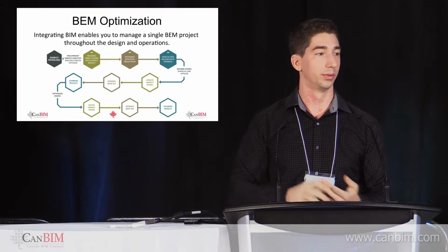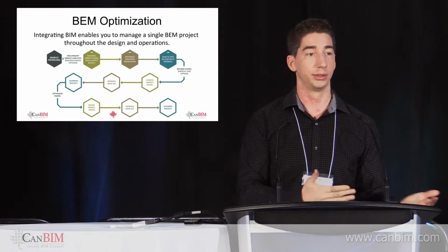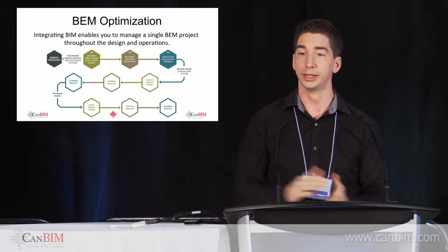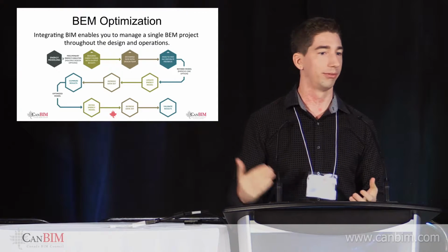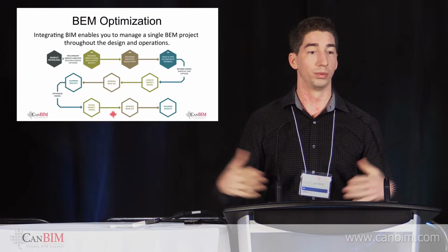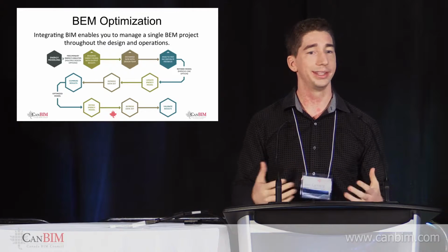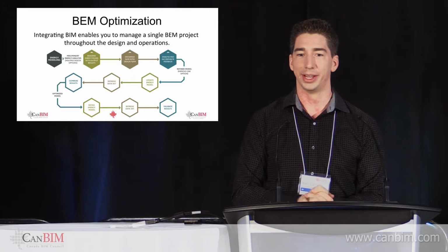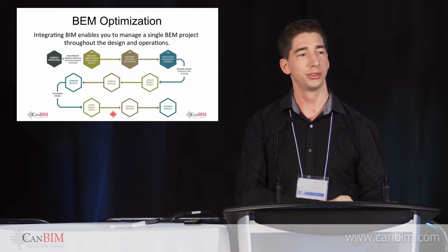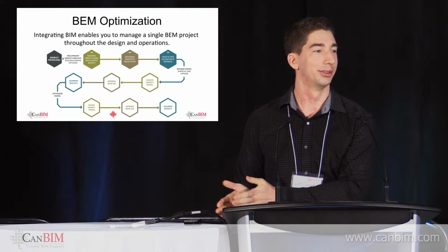A lot of the time, we're doing code compliance work. We're seeing where you're going to end up for your LEED credits, and we're doing that really, really early. If you're not satisfied with 5% above code just to get your building permit, you might actually want to reduce your window-wall ratio or increase your envelope and see what's going on. With energy modeling, that's kind of been typical in the industry, a lot of people use it just for code compliance, which, yes, you have to do it for code compliance.